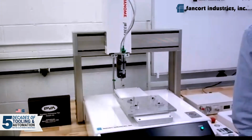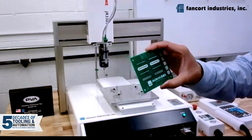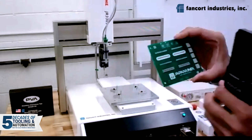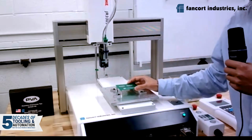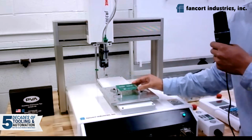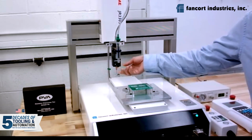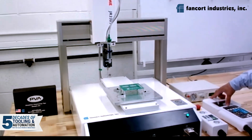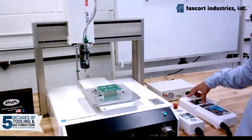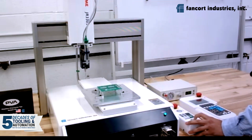So we already have the fixture all set up here. All you have to do is gently place down the PCB. To give you an idea, we're going to be placing 9 different solder pastes here at the top right. Once we have all that set up, make sure you have your solder paste hooked up to the dispense machine here. And once that's all set up, you just have to program the machine to the desired positions you need to be pasted, as well as the dispense amount. Once you do all that, you should be able to automate by pressing start here.